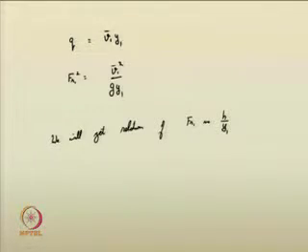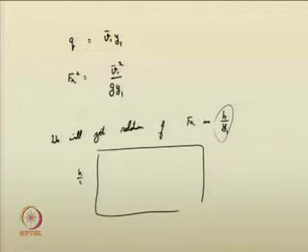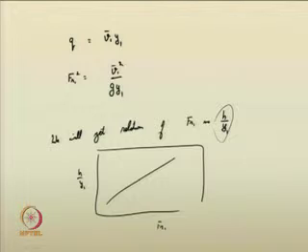relations of Froude number 1 versus h by y1. So, if these plots are given to you, for different values of Froude number, what is this depth ratio h by y1 for this condition? If it is plotted, you can design the sill appropriately. So, you can plot h by y1 for different Froude numbers like this. Now, here you will see that h by y1 is a function of only the Froude number. We are not taking x by y2 or even y3 by y1 ratios and all. So, that is only for the broad crested weir.